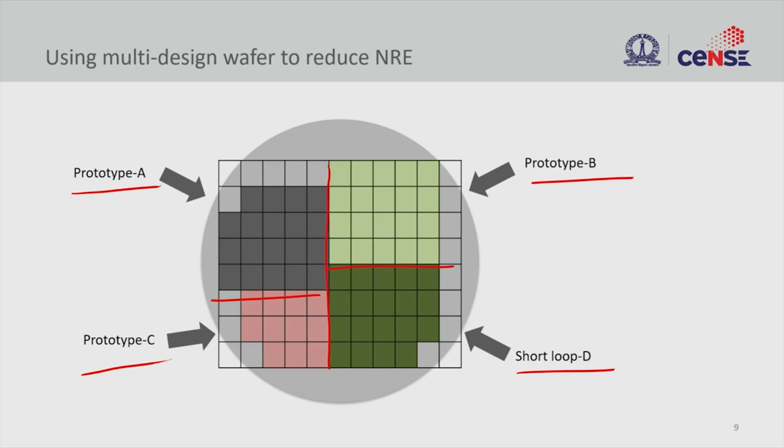So with that, we understood how lithography alone can be very helpful in DFM. Each and every unit process could contribute towards DFM in this way, where you are closely looking at the process variation and then using that process knowledge to make the devices and circuits yield better.